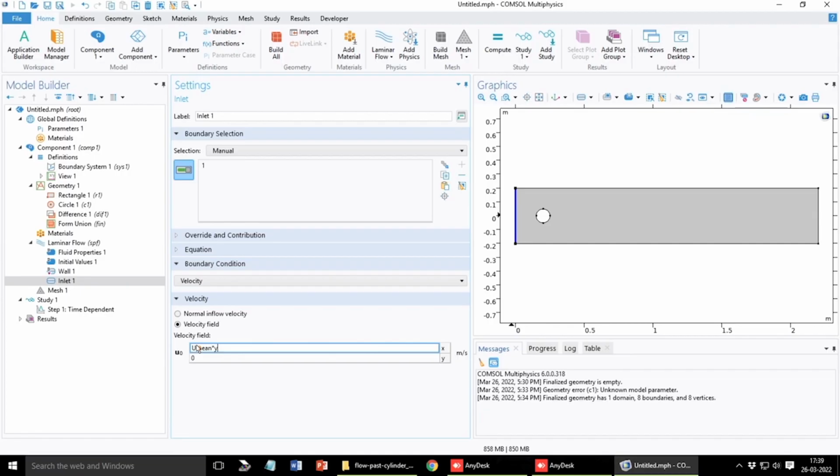Why? Because we want to study the von Karman effects or the flow instabilities in a fully developed flow. If you consider that the flow is still developing at the entry, and you put in fixed velocities, then there will be a hydrodynamic boundary layer and the flow will be developing. So, it will be distorted or it will interact with the boundary layer separation or formation due to this obstruction in the flow. So, we consider a fully developed flow; I assume that previously there is a pipe where the flow got fully developed before it enters the region of the obstruction.